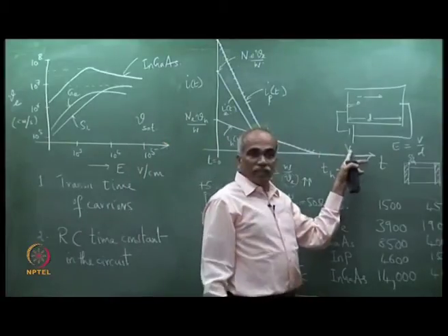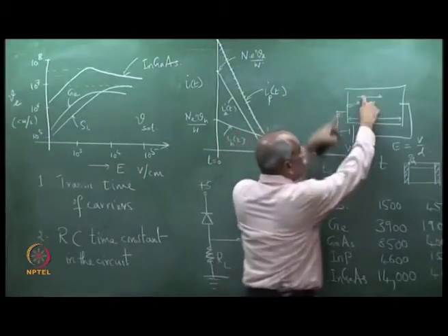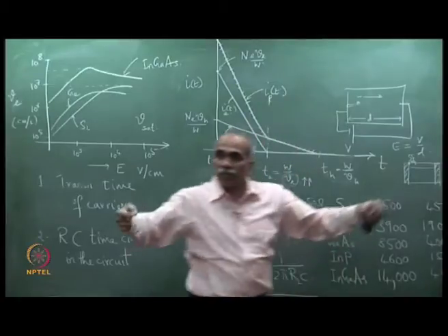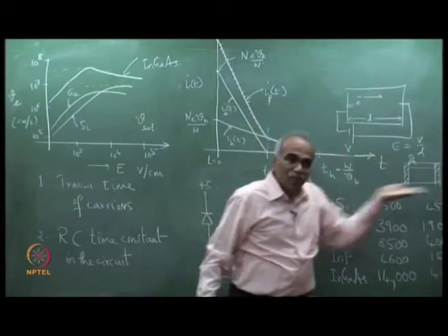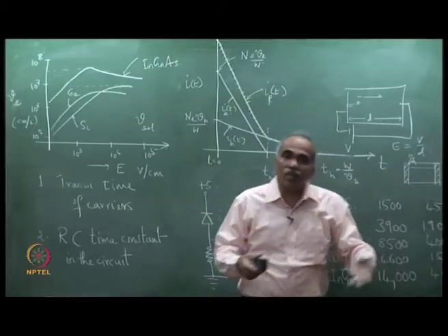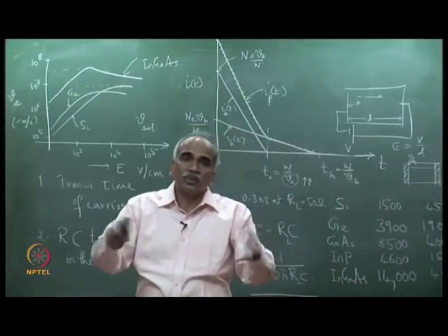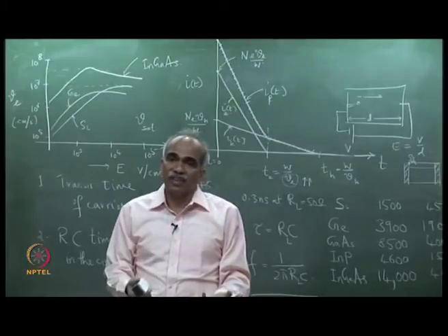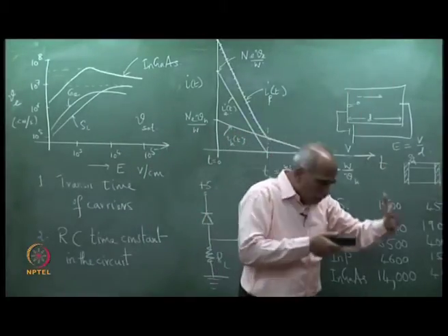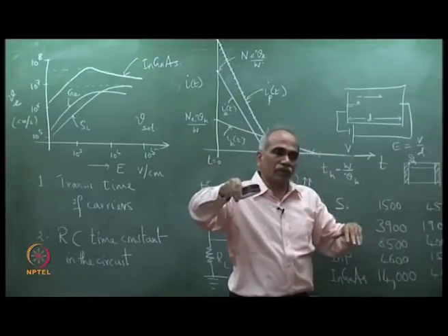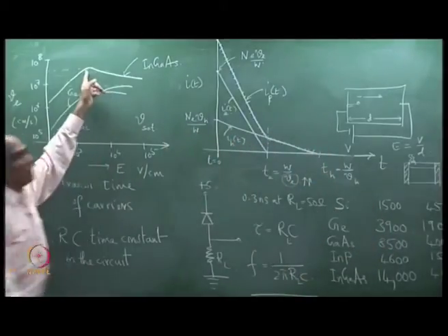As you increase the voltage, the electric field is increasing, the electron is getting drifted rapidly, but after some time, when the electron is moving, it is also colliding with the atoms and the bound electrons in the lattice. So, it cannot go on increasing. After some time it has a saturated velocity, and that is the Vsat that we have.